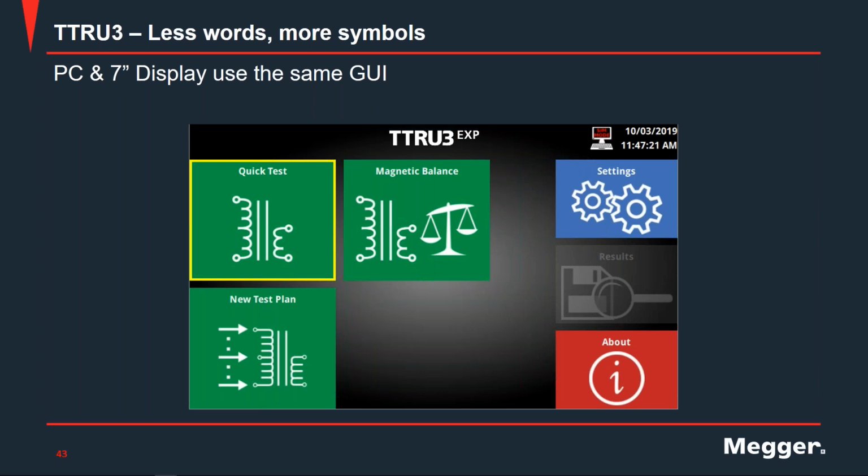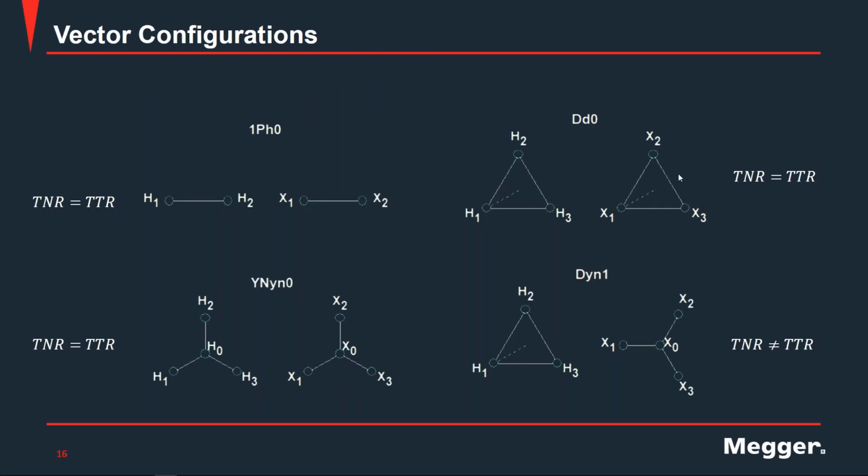But the phase shift that we are calculating during a turns ratio test is between an A phase winding of the primary side and the A phase winding of the secondary side. In theory, the phase angle between corresponding high and low side phase windings should be 0 degrees. And if you get 0.5 degrees or something like that, then that's your phase deviation error.